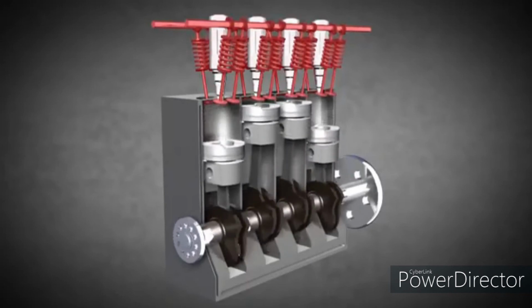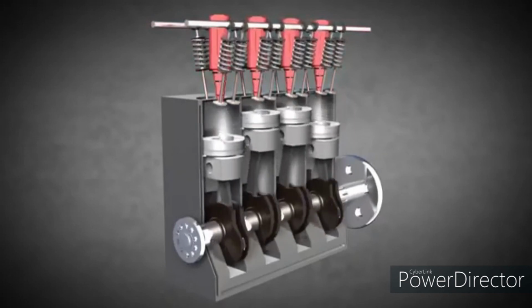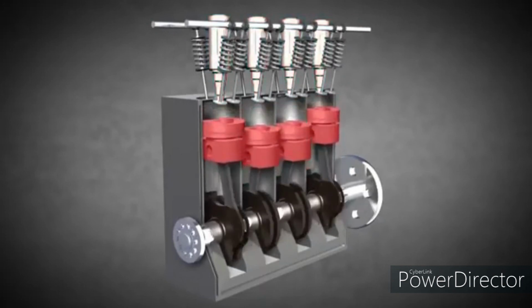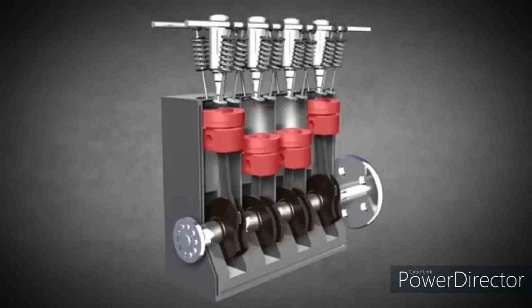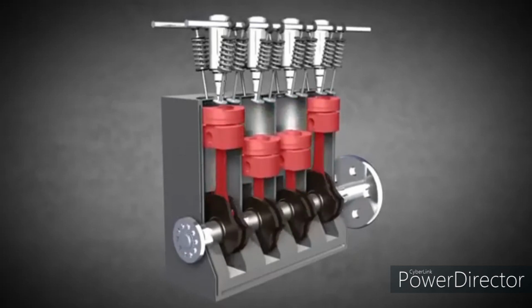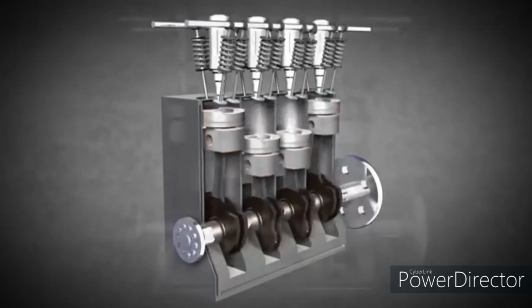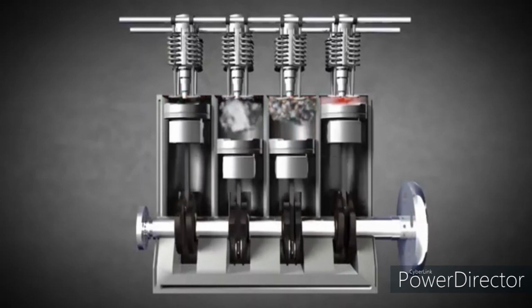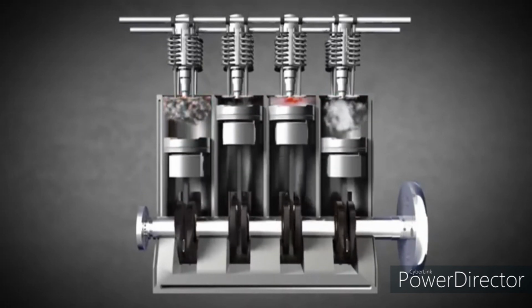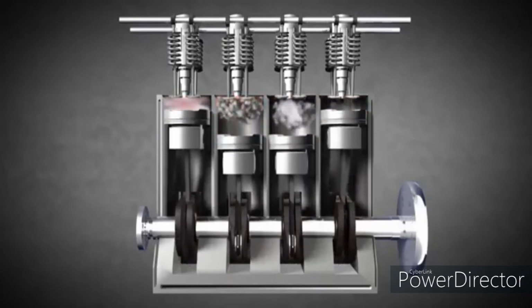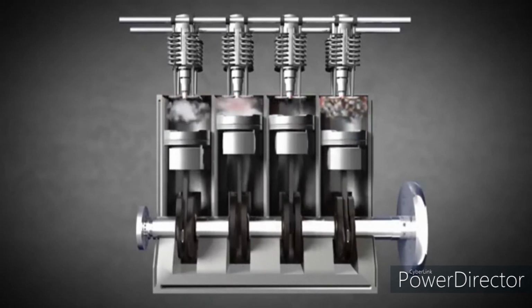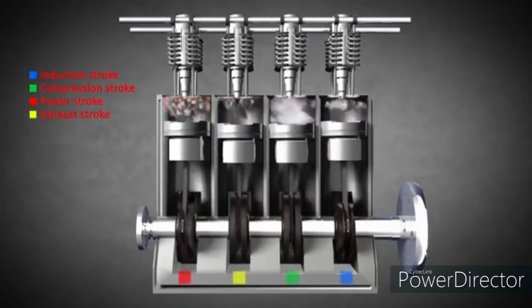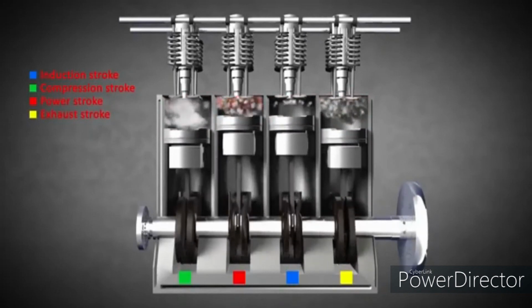The fuel injection system is responsible for supplying the cylinders with fuel. The pistons are forced down during the combustion stroke. The force exerted on the piston is transmitted through the connecting rod to the gearbox. In an inline-4 engine, there is always one piston doing one of the 4 strokes. That is the reason why 4-cylinder engines usually run more smoothly than their 1- and 2-cylinder counterparts. A 4-stroke diesel engine has the same strokes as an Otto cycle engine: induction stroke, compression stroke, power stroke, exhaust stroke.